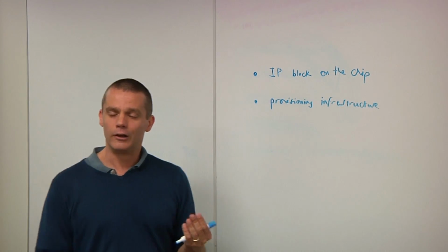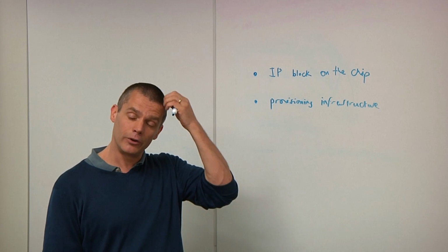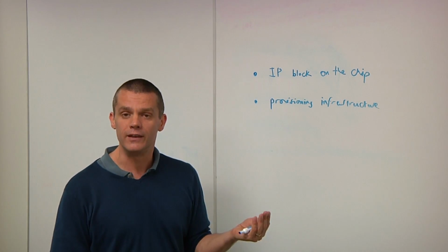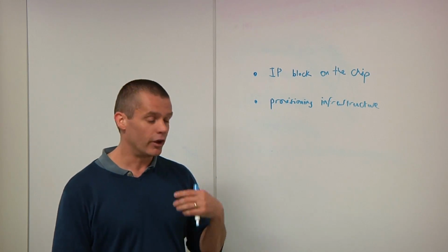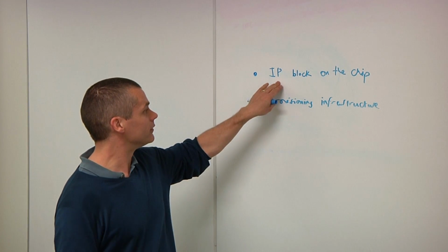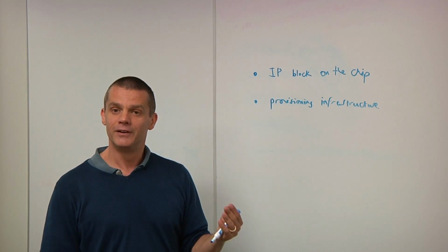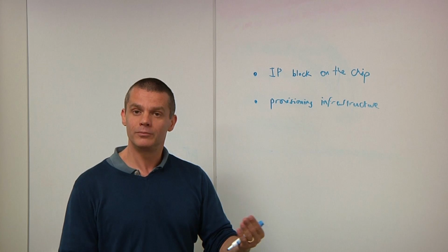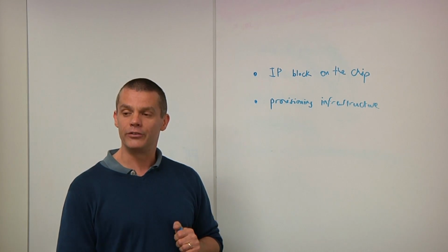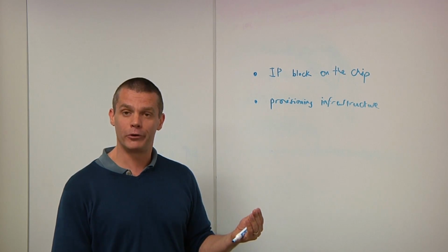You're going to use that provisioning infrastructure, for example, for loading foundational root keys into the device as early as possible in the manufacture of the chip. So it's a block that resides on the chip that's set up to consume root keys that get provisioned during manufacture, and then use those keys to provide foundational security services.